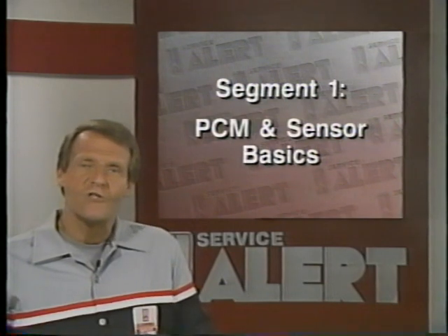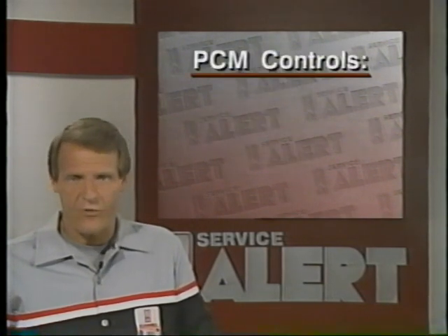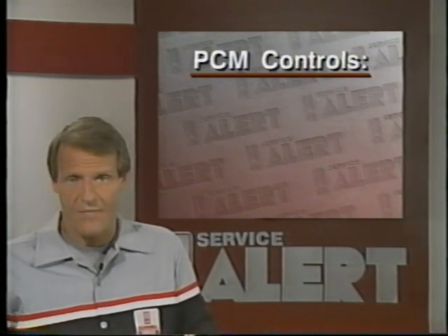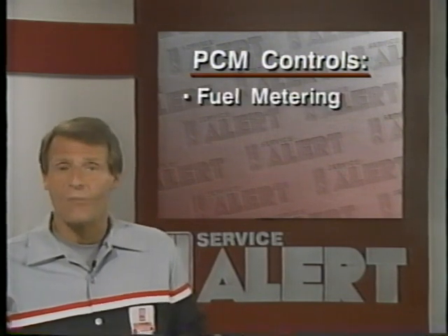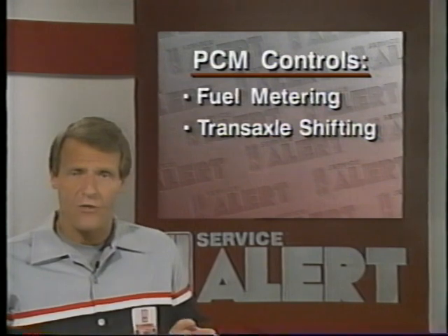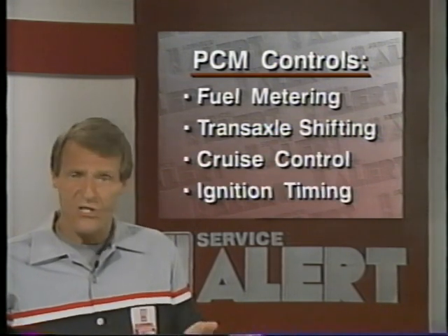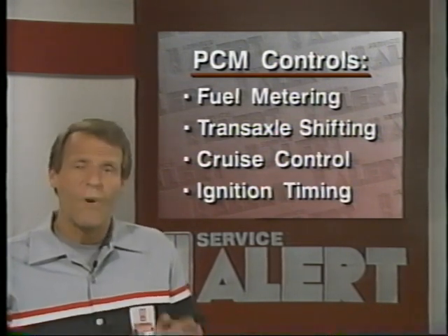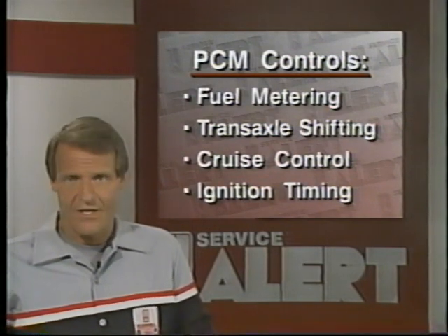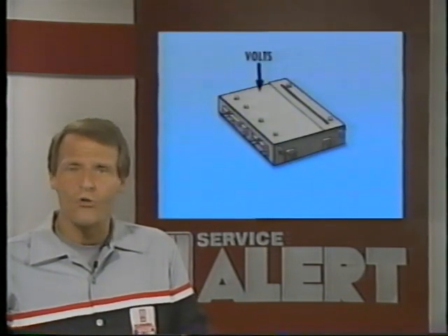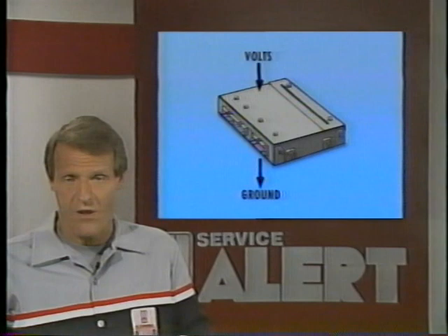The current generation controller is called a powertrain control module, or PCM. It controls a variety of functions, including fuel metering, transaxle shifting, cruise control operation, ignition timing, and others. But before it can control anything, the PCM itself must have a good voltage supply and a proper ground.